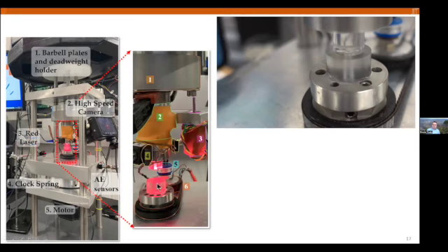Other details here: the sample you see is being lifted. This is the bottom sample, which spins, and the top sample, which is fixed. Before the experiment, we also have a vertical displacement sensor to see the shortening and eventually dilation of the sample. And on top here, we again have a couple of acoustic emission sensors mounted very close to the fault.